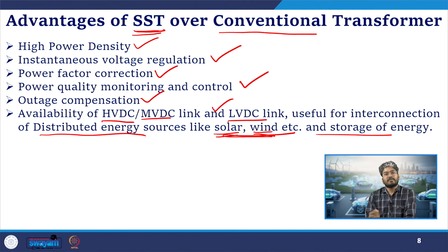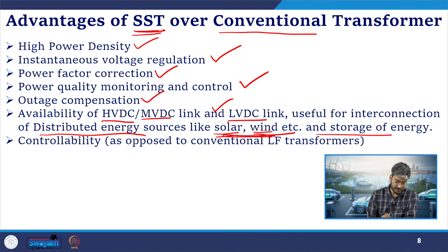If this facility was not available to me, I would have required one more additional stage of conversion, that is from the fixed DC to a fixed frequency AC. That stage will be eliminated as the SST has DC ports with it.